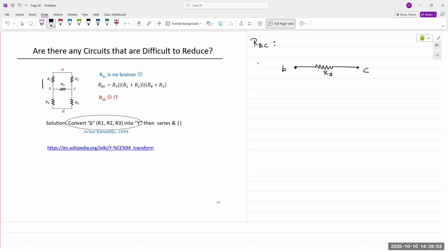The other pathway goes here, and the other pathway goes down. So we start at B and go around the top. We come back to C. Anything that is there in that pathway, doesn't matter if it's 1 component or 2 or 2,000 or 200, they're all in parallel between B and C. Or not all. All of them combined is in parallel with B and C.